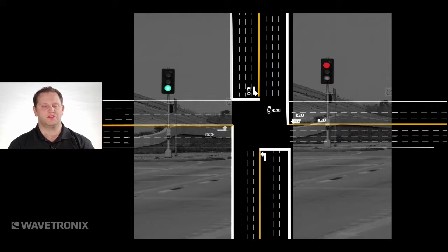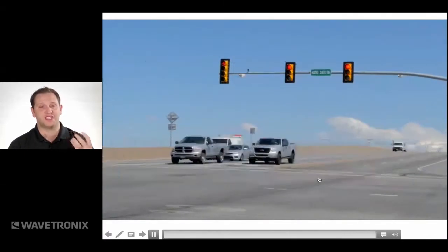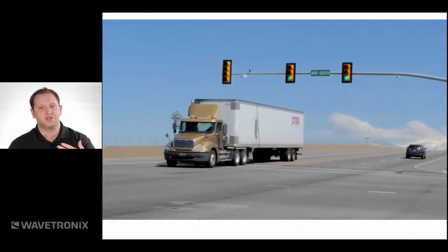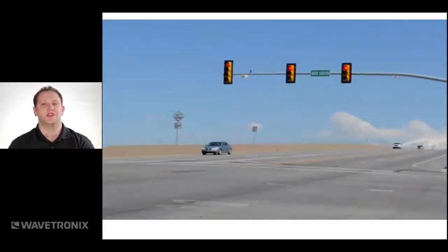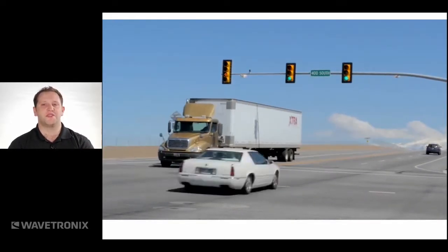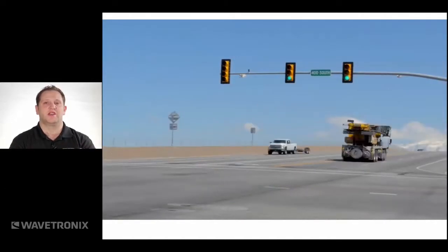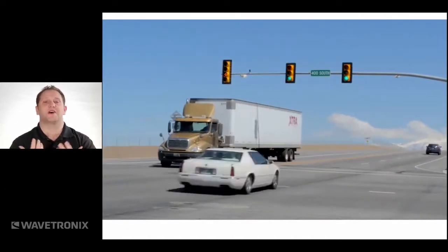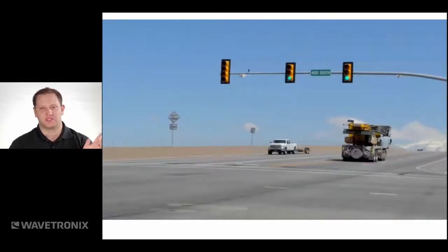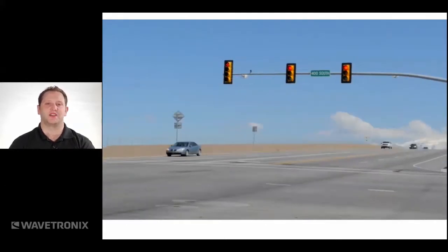So years ago, they found that using a flashing yellow left-hand turn arrow can tell drivers that they can continue through the intersection, but they need to do so with caution, removing the assumption in drivers' minds that both sides will gap out at the same time. So that flashing yellow arrow is just a proceed through with caution. But the detection can change a little bit based on this as well.